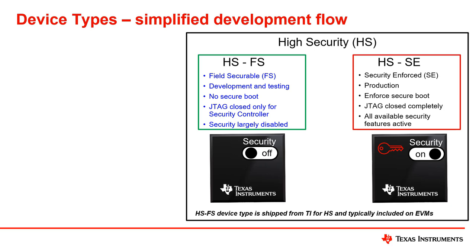So field securable devices do not implement secure boot. You don't have to have your code signing and all of that in place. You can just get code into Flash and start doing quick development. JTAG is open, so you can do debug except for the security controller, and security is largely disabled on these devices, so that you can do design and development and move through your development process as fast as possible, and then enable security when you're ready.